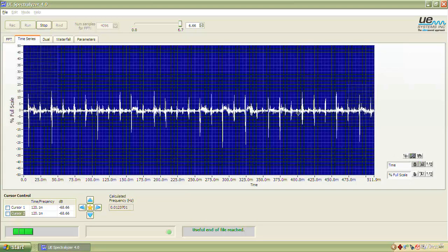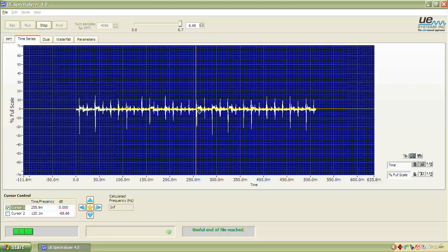All right. Notice with the time series analysis, we're watching events happen in time. So we can actually see when those discharges are occurring there, and what time they're occurring at by turning our cursors on. Now, we only have 2 types of cursors with this, and this is the movable cursor. Remember, I cannot see either of the cursors right now, so if I highlight cursor 1, turn it on, I'm going to hit the star and it brings it to center, and now I can go grab that thing. Look at that, I zoomed out further.